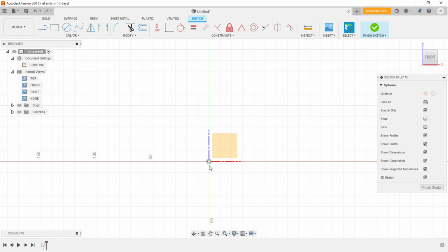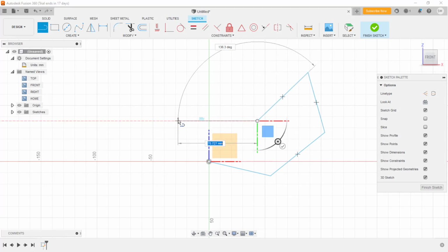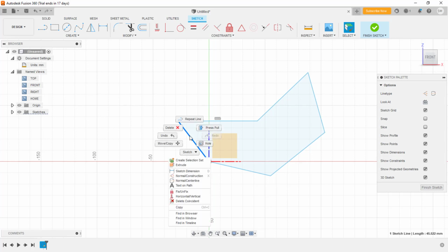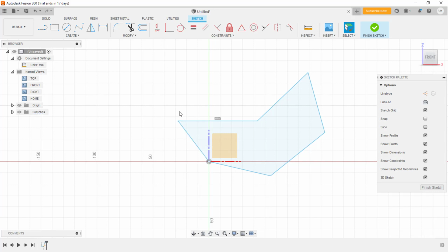So you can simply click on it and create sketch, and you can start with the shortcuts like L is for profile and line. You can simply draw the rough sketch like this. So always remember, try to refer the origin as much as possible and try to draw the rough sketch in the beginning, selecting the appropriate planes. Okay, so now this line should be vertical. So there are two ways to approach this. One is simply right click and you can use the make horizontal slash vertical. This is one way, or else you can simply click on the constraints which you want to apply. Just select the constraint and click on it, and this should be horizontal. Automatically it will assign. This is anyway horizontal.